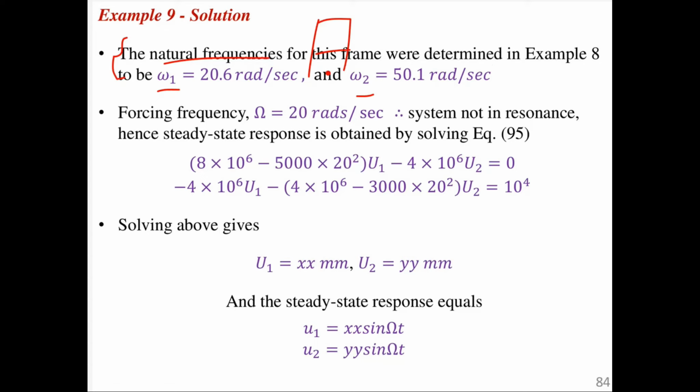So you should try, because in the example that I gave you, or in that book, you have a case whereby you have a 4-story building. In that case, you should try to see how the mode will be, because with the sign, for example, if you get it's negative, this side is positive. So in the first case, you get all of them positive, so the deformation of the structure is on the same side. You calculate the second mode, you found that A2 was negative, so we found our structure going like this already. Now U1 was negative, U2 was positive.